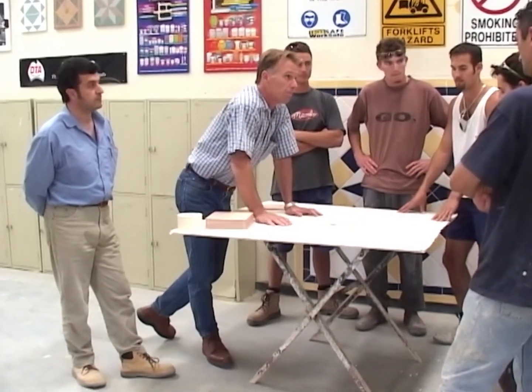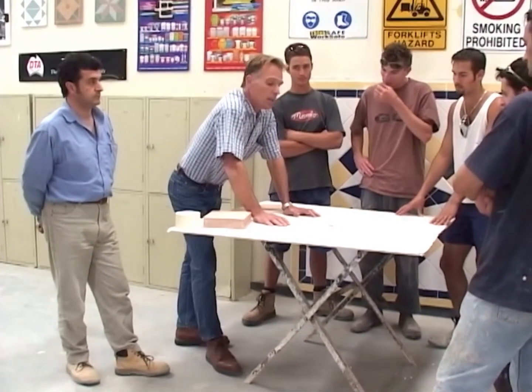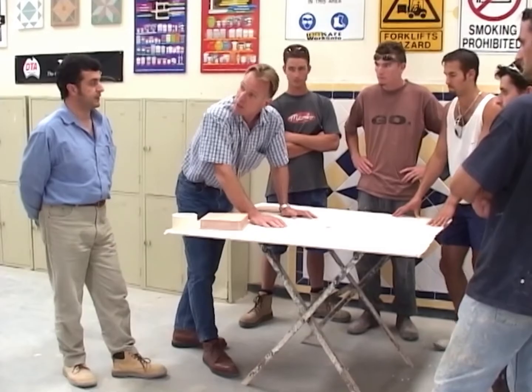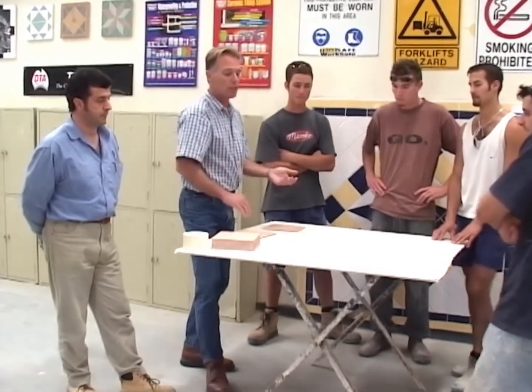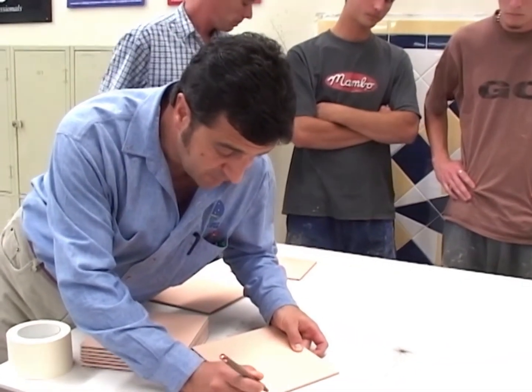Do you take it off each tile, or do you start again at a smaller size? You would start again, yeah. Using the calipers, exactly. Readjust your calipers. Position the tile on the outer circumference and the inner circumference. Just mark your tile off, allowing for your 2 mil joint.